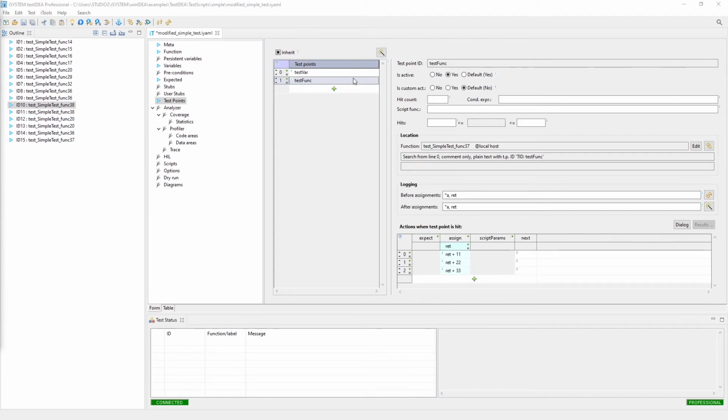Next, we have the coverage measurement. So coverage is actually done in two ways. The recommended way is if you have access to a trace interface. The trace allows you to record program and data execution while the system's running. It's completely unintrusive. It usually requires a special device, either a special pin package or a special emulation device.